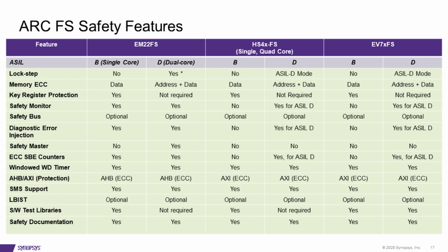Diagnostic error injection, a watchdog timer, a windowed watchdog timer, protection on the buses, and being able to enable things like memory bits and logic bits that I talked about. And then the safety documentation is another important part of that. All of the reports that are required for certification are an important part of what we do in our processor development, and we provide that to our customers to facilitate their own certification efforts at the SoC level.